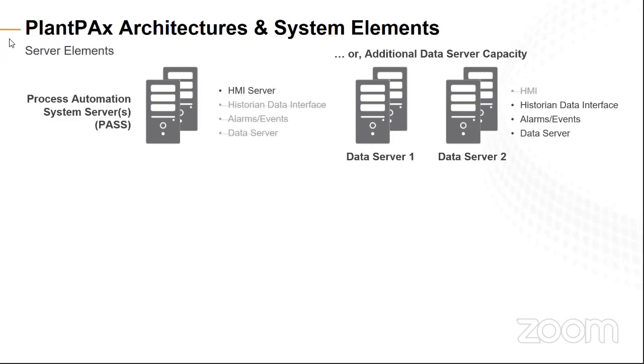Basically, a data server is just either OPC. So I'm looking at Modbus, I'm looking at OPC DA or OPC UA, or potentially FactoryTalk. So the FactoryTalk Linx is my data server. I can have 10 of those, and I can make them redundant. So the requirement there is 1 FactoryTalk Linx and 1 OPC per data server. So I can't stack them up on top of each other. And it's required on its own OS. So whether that's virtual or physical, you just can have as many as you need to.